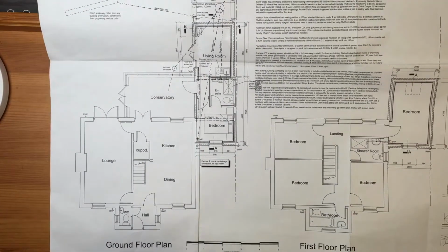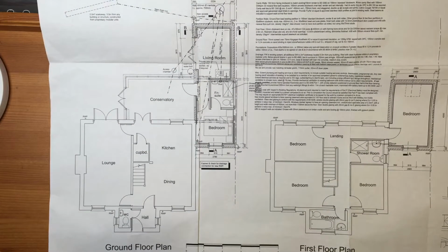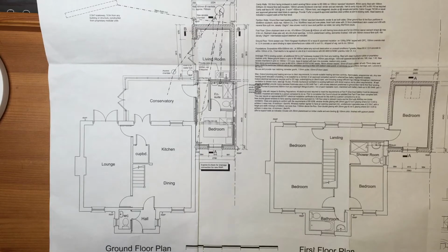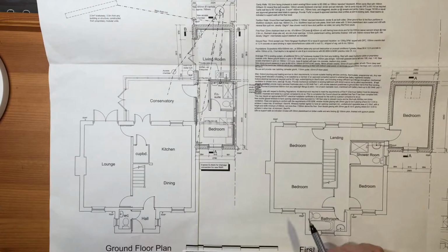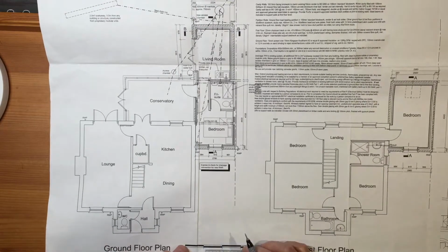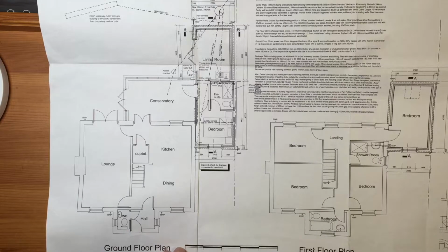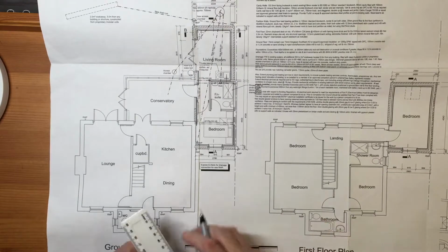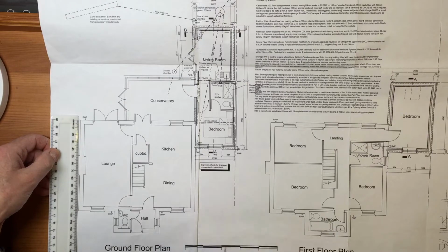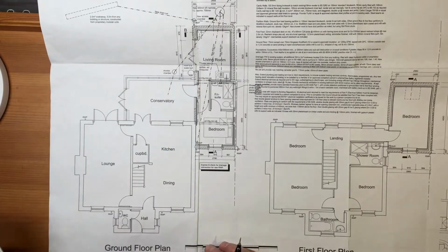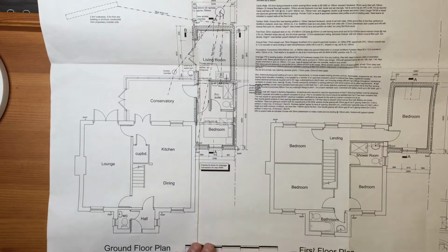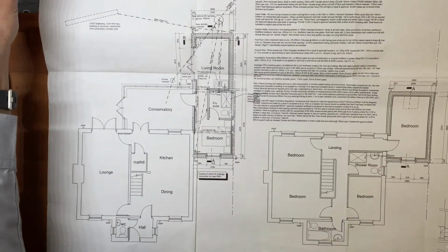Yeah. There is one thing I noticed here. It even gives you a distance in metres on the drawing, so you could take a ruler to that, and you know that for every 25 millimetres, it's 1 metre. Yeah. So you could actually calculate that, knowing that distance there. You could calculate how long that is, or you could use a proper scale ruler, which you can buy. Yes, Jake, any other questions?